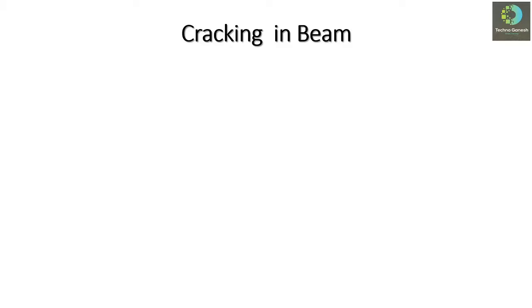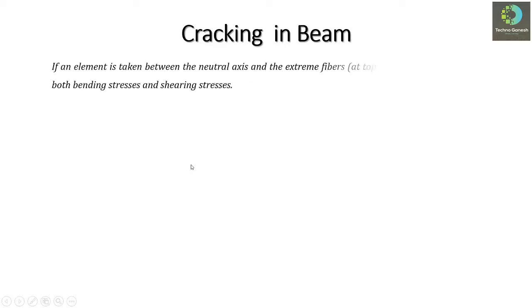In this lecture, we are going to discuss the reasons why these cracks form in a particular region or portion of the beam in a particular pattern. So let us start the discussion on cracking in the beam section. As we know, whenever a beam is subjected to load, bending moments develop in that section and shear force also develops in the section.